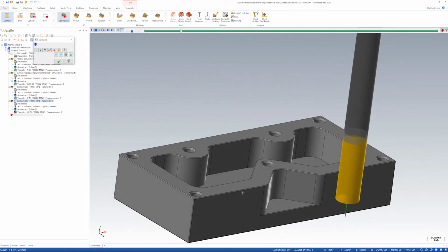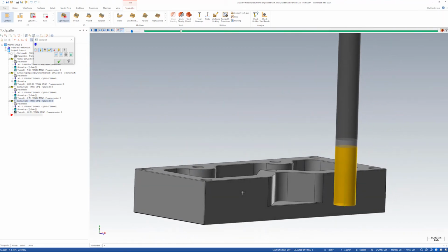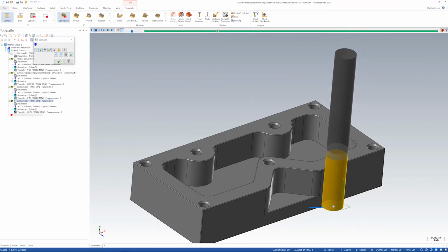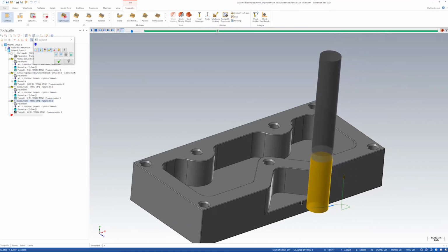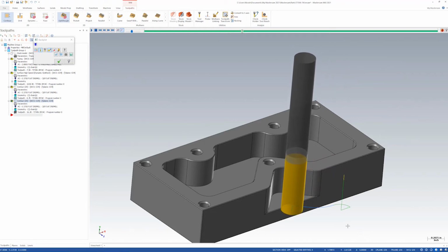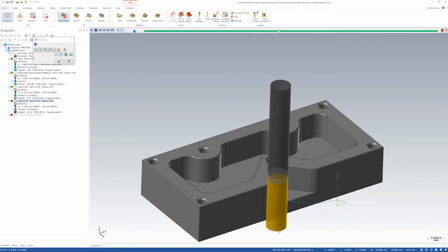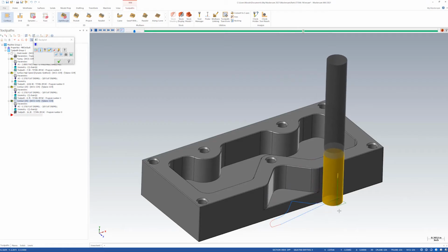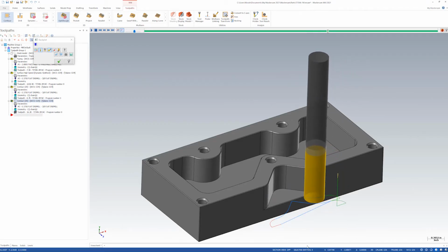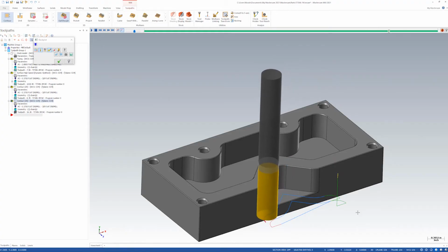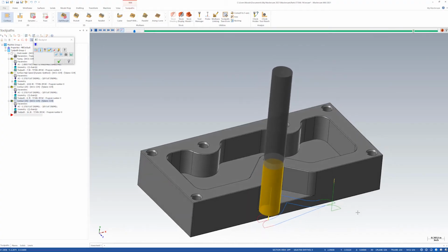So I'm going to drop down. Got that perpendicular lead in and that horizontal radius, and then it's going to come and take that first pass. And then it's going to stay down, swing over into the next pass, finishing that step. Perfect. And then lift.